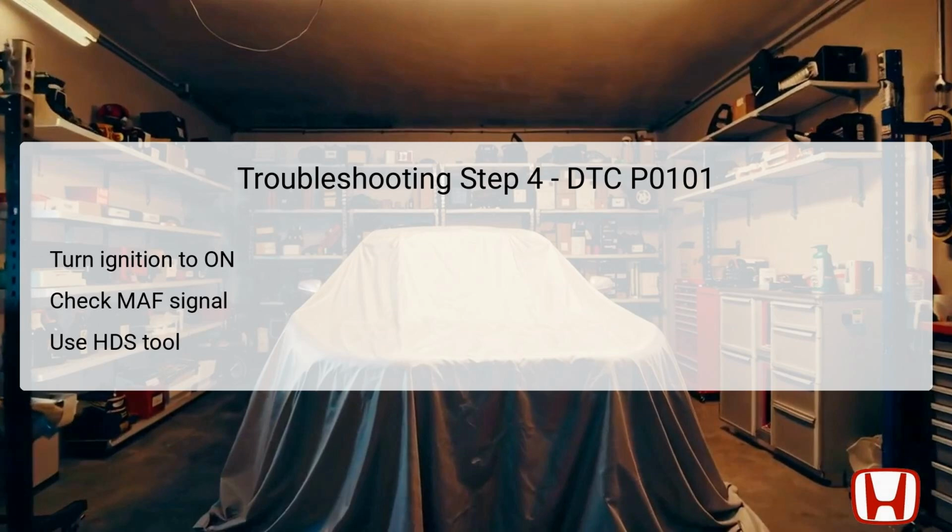Begin by turning the ignition switch to the lock position, and then switch it back to the on position, ensuring the engine is off. With an appropriate diagnostic tool, such as the Honda Diagnostic System, HDS, examine the readings for the MAF sensor against established threshold values. The expected output should be approximately 0.2 grams per second, g/s. If the readings fall within the expected threshold, it indicates that the MAF sensor is functioning correctly at this point.